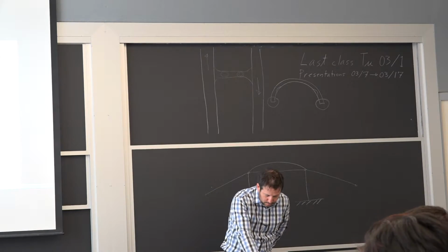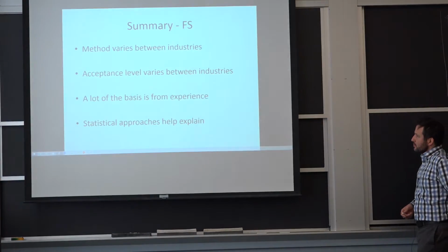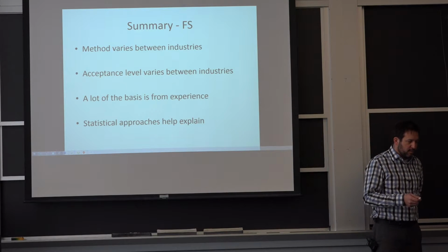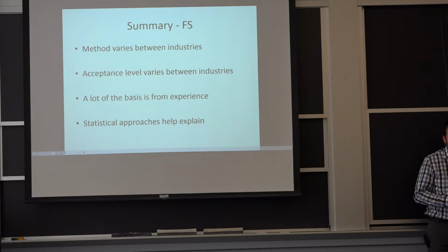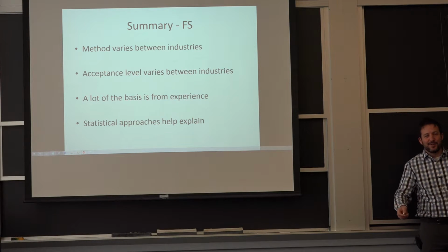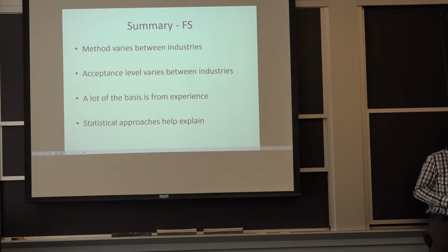So what we try to do, if you're building something, I think you have to identify in which category you fall. Is this a new bicycle for a race that the guy is going to be ready to fall to the ground and be safe anyway? That's a good situation to be designing. So you can say at the very extreme limit, yeah, the whole thing is going to fail as long as it doesn't create an injury. You may be okay, and that's a problem with composites actually, because they fail in a brittle manner. People can get injured, so you want to work on how it's going to fail so it's not consequential.